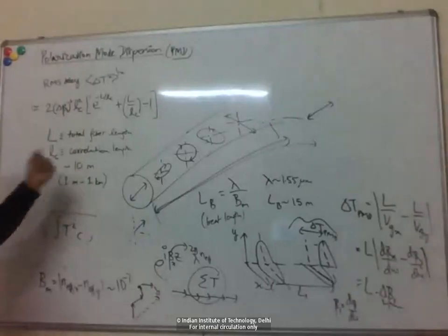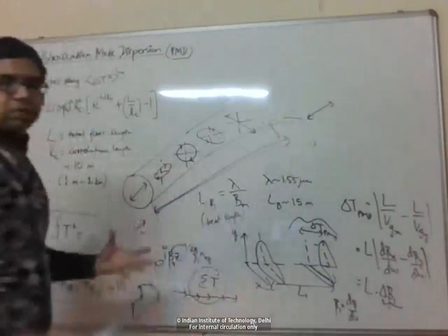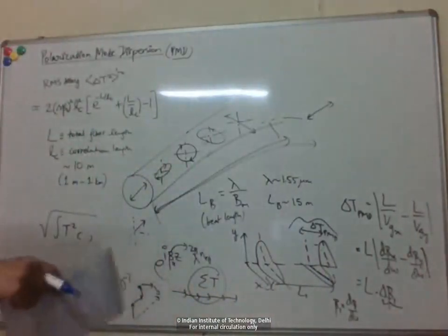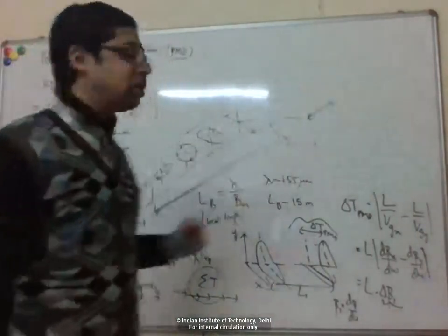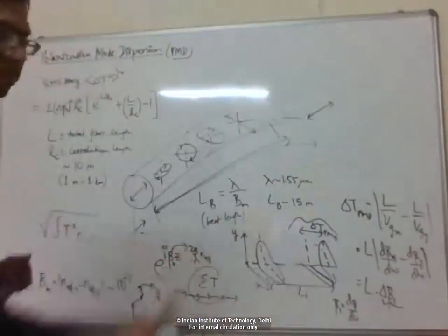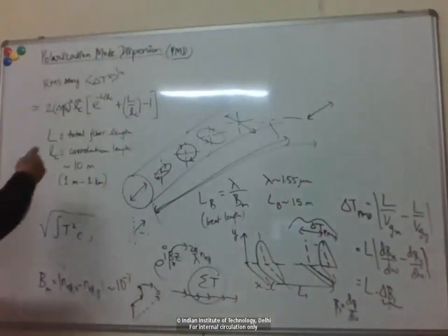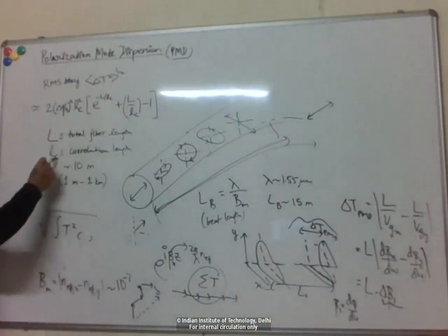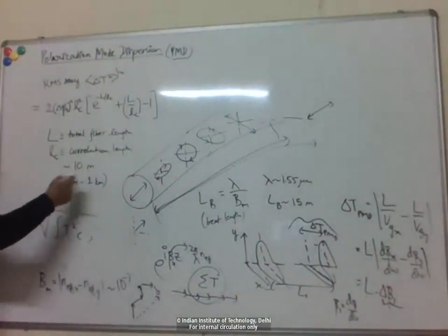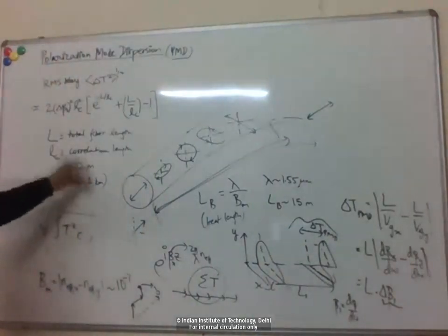This is also a randomly varying quantity because of the random stresses on the fiber. Each section might have a different length, but this is on average the length of each section where the birefringence is roughly constant. Typically the total fiber length will be much bigger than the correlation length, because we're communicating over hundreds of kilometers, and the correlation length is less than a kilometer.